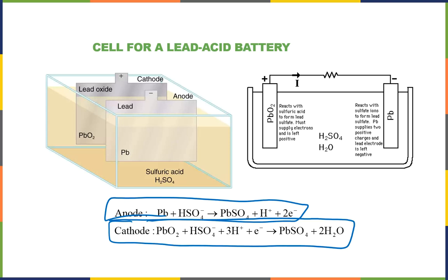So what happens when you put the whole thing together, since you have fluid that can freely flow between these plates, is that you will have a reaction that goes until you reach equilibrium, where the voltage difference on one side compared to the other is sufficient to stop those reactions. And so the battery should have, for each single cell, about 1.5 volts. But as soon as you start to use the battery, then you start to put a resistor across the top so electrons can flow across.